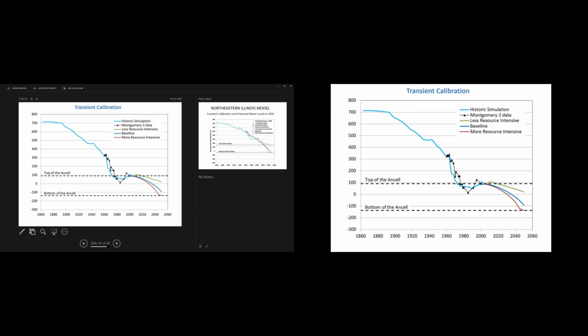Because, and this was Tom Prickett, whose name has come up a few times, he's a very famous modeler here, did a lot of the early groundwater models. He said a lot of models go wrong with storage, and in Northeast Illinois, where you lowered water levels 900 feet, you get a lot of change in storage. But even in the glacial aquifer, storage is very important.